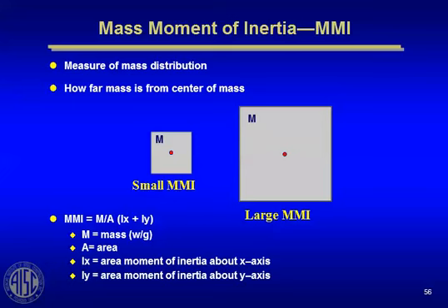It's a good check. When you're doing a computer model, it's real easy now to check your mode shapes, right? You just push a button and you can see these mode shapes come out. Watch the building dance. If the first mode is a torsional mode, you need to go back to the drawing board and modify your lateral load resisting frame so that the torsional mode is the third mode, not the second mode or the first mode. It's a very good, simple rule of thumb.